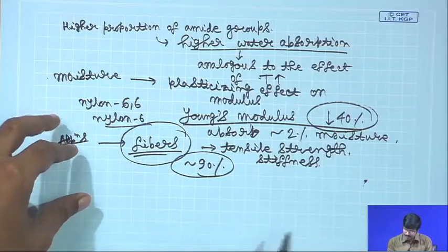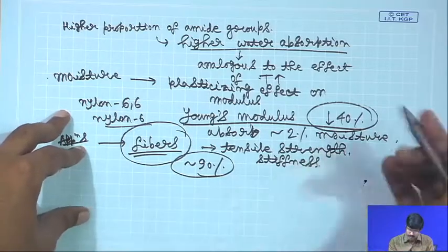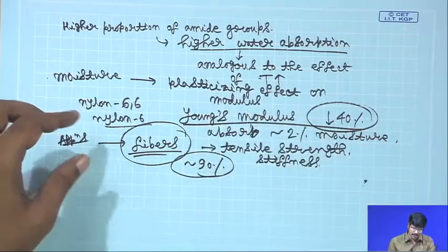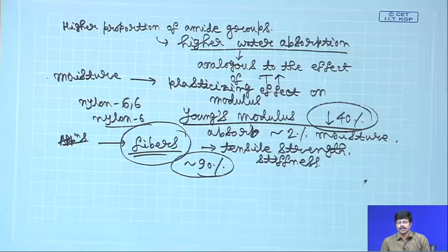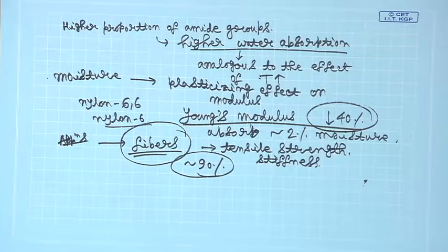and typically, because of their high cost, they have not become general purpose materials, like polyethylene or polystyrene, which are typically available at one third of the price of nylons. So, for plastic applications, nylons have not gained much ground with respect to the other commodity polymers.